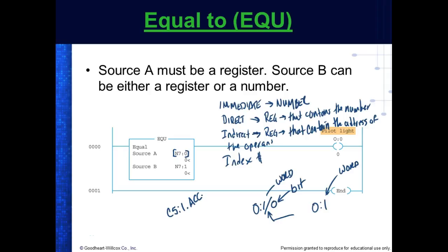It's on 296. So the dot, I could come over here and say dot 0, right? But that would be a waste of time because this is the whole word. But when we get inside a counter or a timer, we have several 16-bit registers in there, so we have to specify which register we're actually going to, right? Everybody understand? It's on 296.